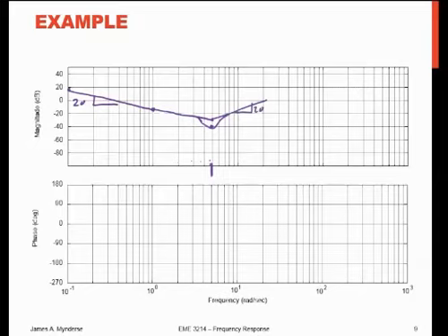I get to my next one at 50, which is my next corner frequency. So I'll go up there till I hit 50. I'm not guaranteeing accuracy. And now I have plus 20 slope, and I'm going to add two poles. So 20 plus negative 40 is a negative 20. So I'm going to roll off at negative 20 until I get to 200, right there.